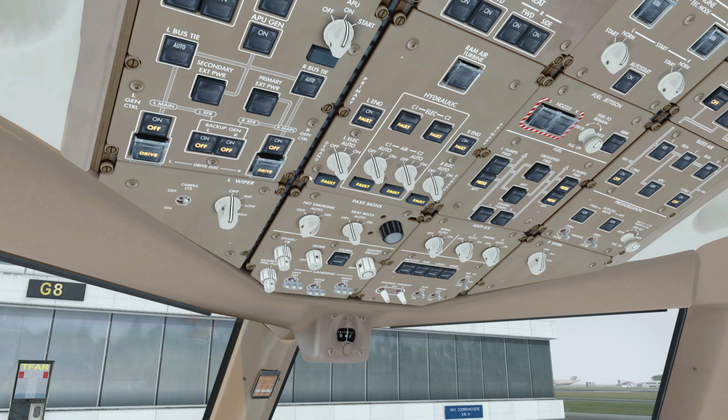Then we have the hydraulic panel right here. As you can see so far, it's all system by system. We had the electrics, and now we have the hydraulics. Again, just leave this panel for now. We're going to start up the hydraulics just before pushback, basically. Again, these systems were turned off, the electrical systems and the demand hydraulics, because we want to use as much electrical power as possible for the startup. So we're not going to touch this at the moment.